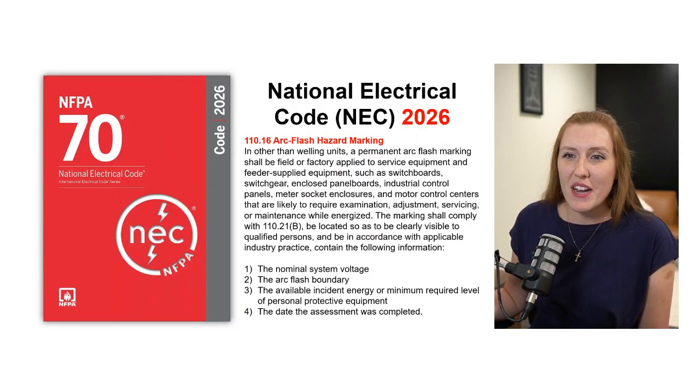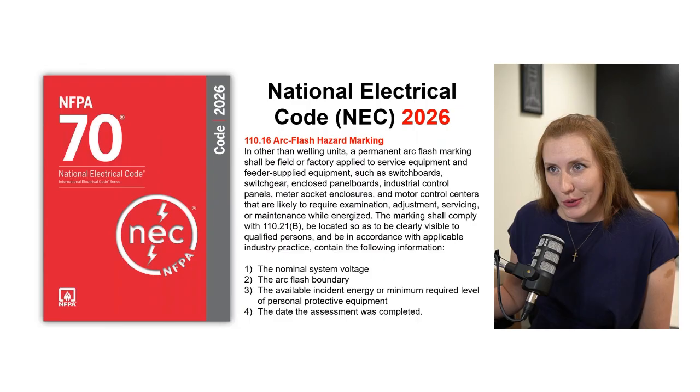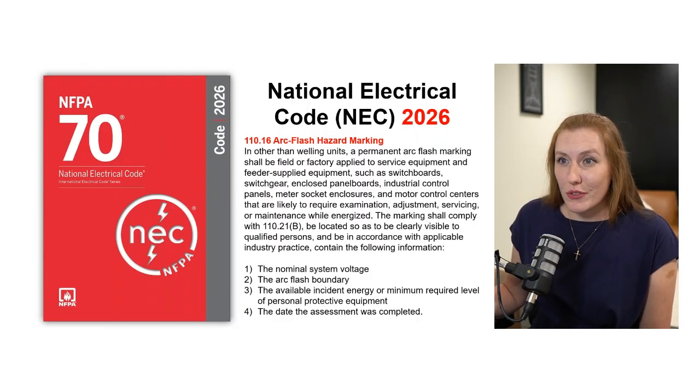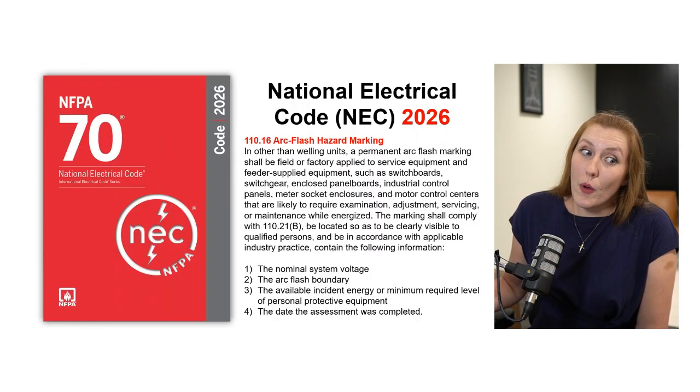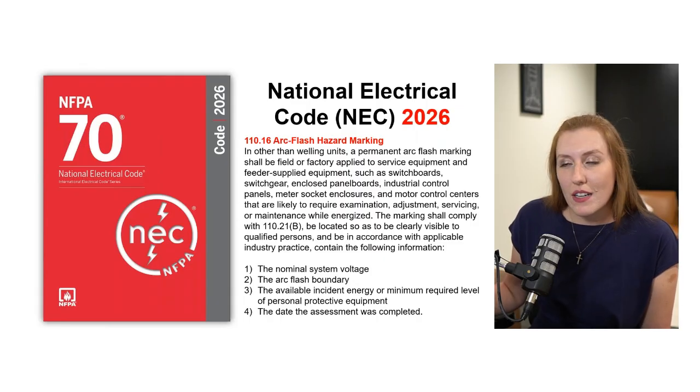So there you go. There's your update. There's the breaking news. The 2026 National Electrical Code took out the potential for those silly little loopholes. No more generic labels. We need to get specific about what hazards are actually there so that workers can really protect themselves and others instead of just saying, be safe, be careful. That's not enough. We need to know specifics.